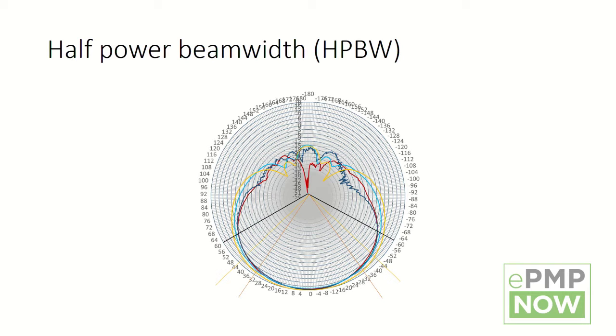So tell me, the 3 dB is half the power. Yes. And what's the implication in terms of power? What does 3 dB mean? Why is it so important to have 3 dB more or less gain for a customer? So everything comes down to the link budget between the access point and the subscriber. So the distance I can cover and the modulation I can get. Exactly. So the higher the link budget is, the higher modulation I can use, which means I can send data at higher throughput.